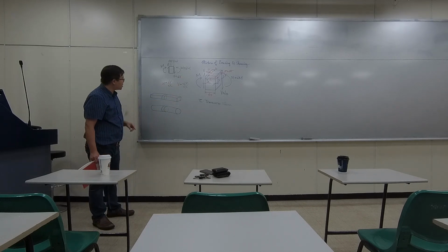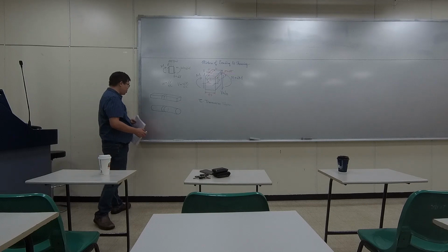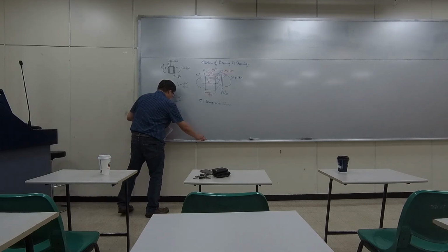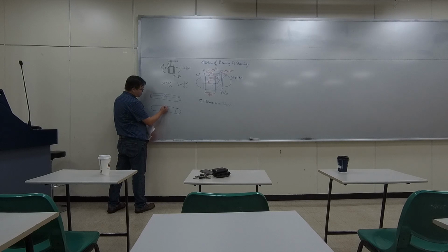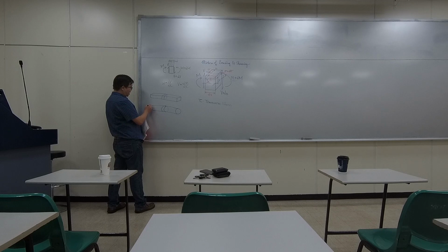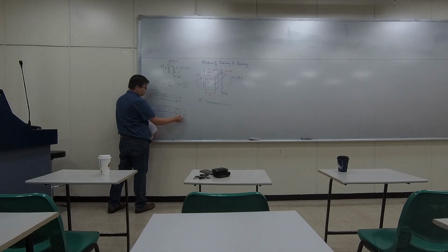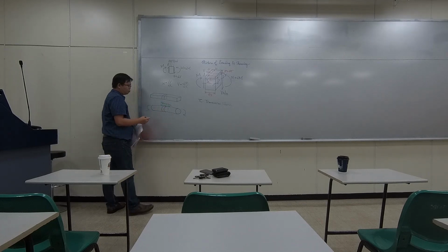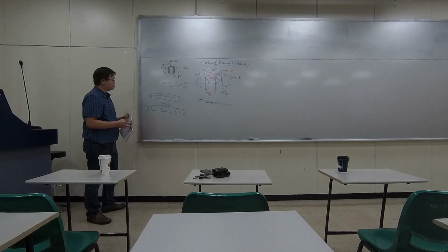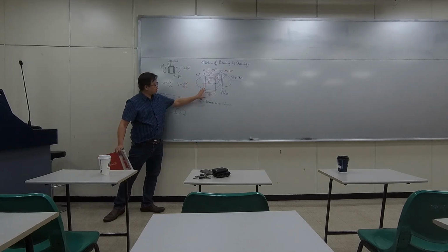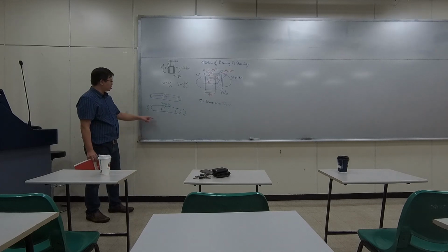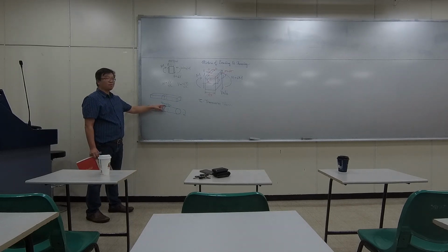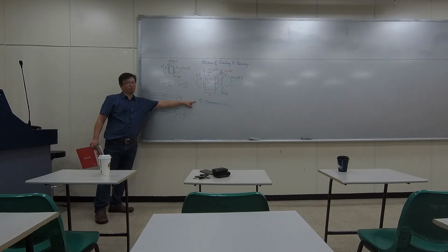But the issue is, most of the time we were talking about a point where we have a great deal of compression or tension. So let's say I have moment bending this way, then I have the tension right here. We have normal stress left and right. And after I tell you about this transverse shear, on the point at the top, this goes to 0.